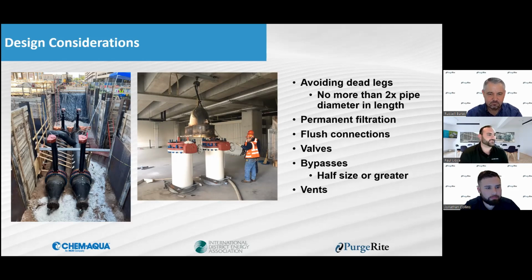If it's a design issue, like this one here with the dead legs. Dead legs are a huge issue with microbiological growth and corrosion, and just contaminating the system, because it slowly leaches out bacteria and organisms. You could hit that as hard as you want with biocide, but you're only going to kill the outer layer. You're not going to penetrate deep enough into an area that doesn't have any flow. Now I know the picture on the left is going to get buried. You don't want that out there.